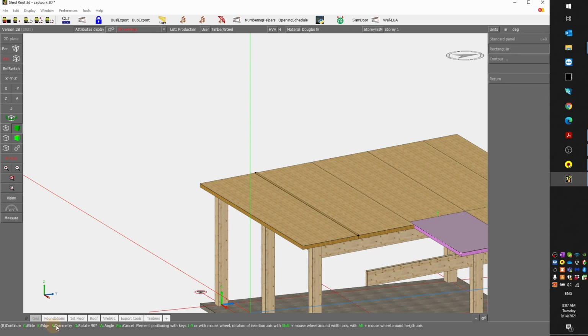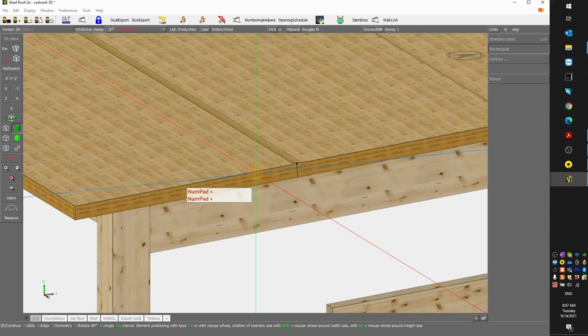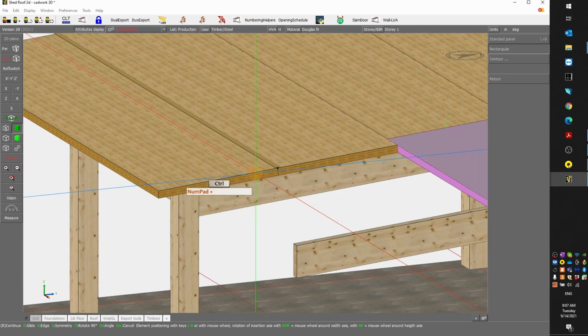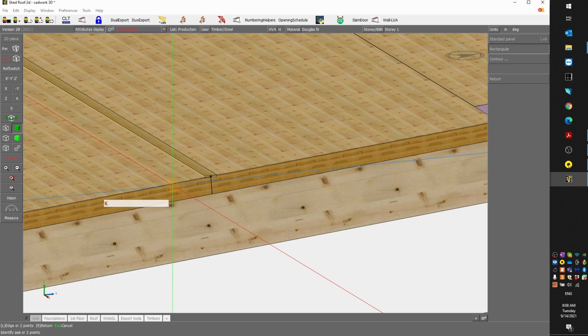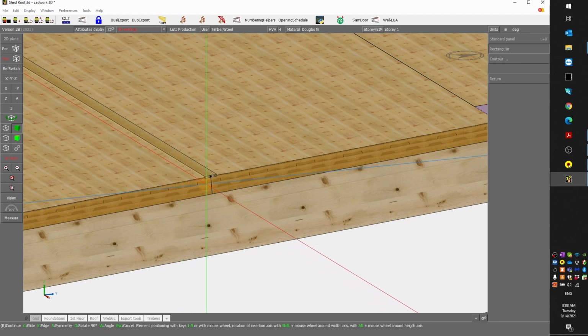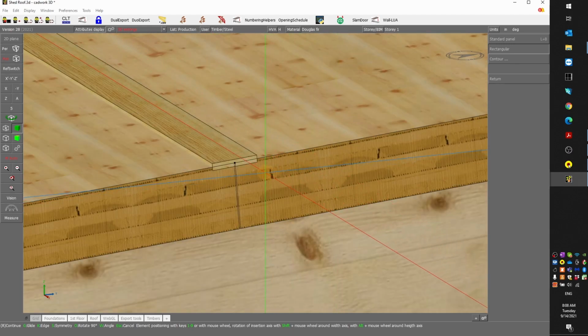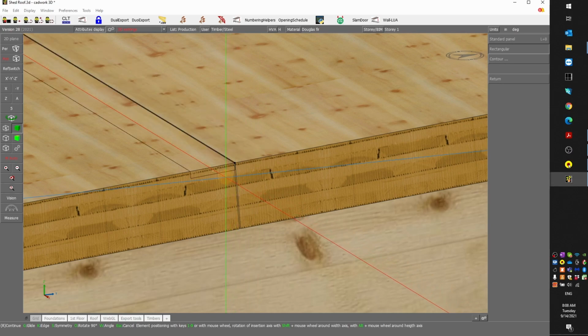using an edge. So I press K. So here you have to press plus in order to zoom in, or if you press Control, you can zoom in and out. If you do not press Control, then it's going to move the spline around. So here I press K, and then I pick an edge, and now you see it aligns the part properly. And now I can scroll, and it moves the part around until it's centered.